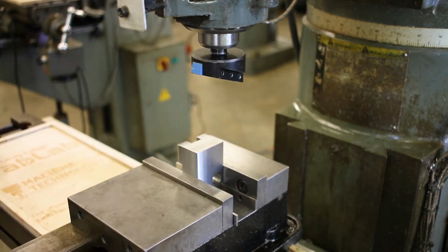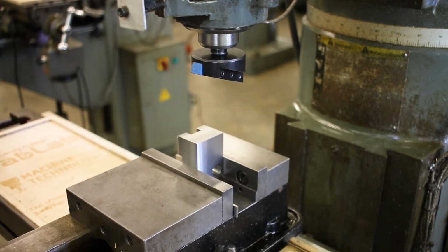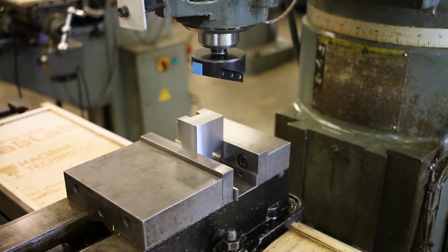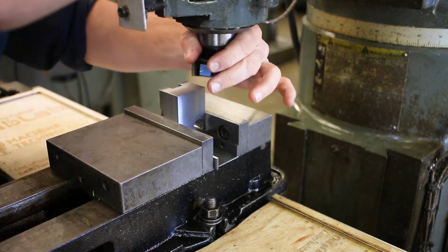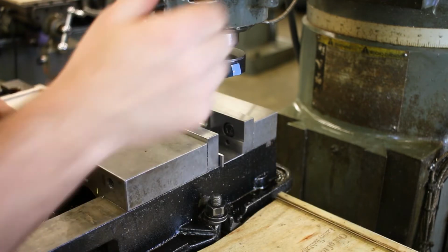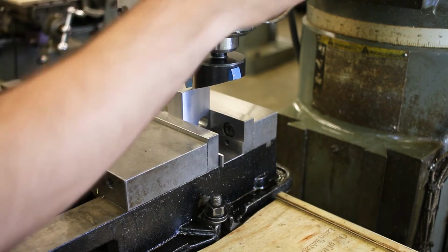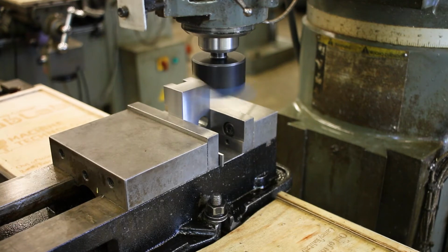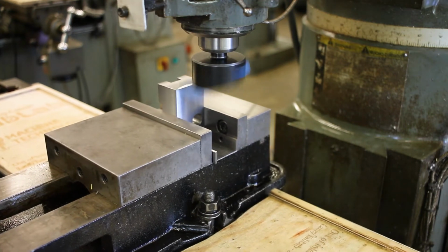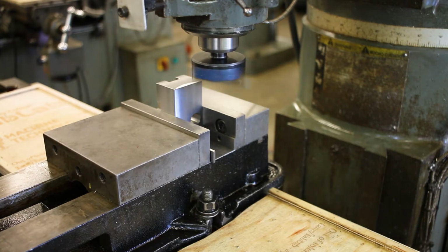Okay, raise the part up so it's relatively close to the fly cutter. Back into high gear there. Okay, kind of get it close with the quill. Right there is good. Turn it on. Slowly inch up with the knee until you just touch off on the surface. Right there. Back off. Adjust your 0. Go in 5 thousandths.